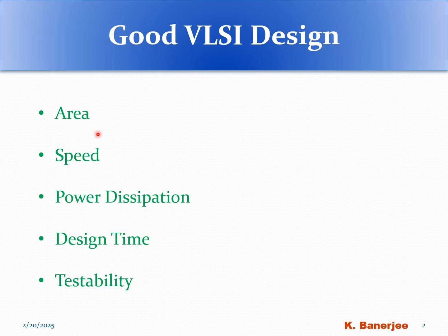Minimization of chip area is important to reduce the consumption of wafer area and to increase the yield of the design of the chip. Now, what does this yield mean? Suppose there are 100 chips which are fabricated, then how many of them are good is known as yield. That is a very important term in VLSI designing, and minimization of chip area is very important.